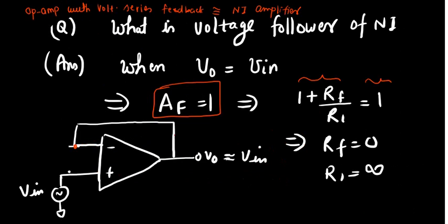There is some input signal which is coming from some circuitry, right? You want to isolate it from the next stage, which is some circuit. You want to isolate these two circuits so that there is no effect of loading, no effect of this circuit on this. So there should be a buffer, but with very high input resistance, something which will isolate both these stages.